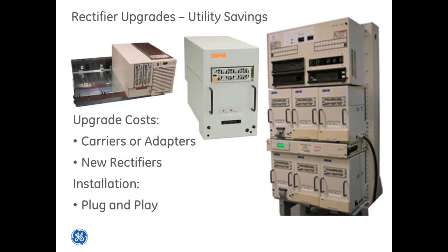Rectifier upgrades: we can get significant utility savings by upgrading rectifiers. And it's very easy to say, okay, well, I'll just rip out a power plant and put in a new one, and I can get my savings that way. But the cost of reconnecting all the loads to a typical power plant can be as high as the cost of the power plant itself.